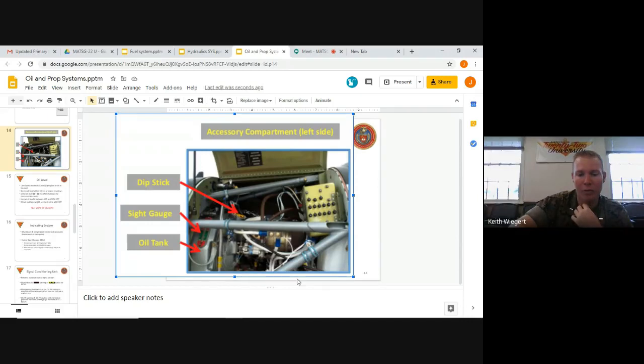Now, if I'm getting low oil pressure, my engine-driven low-pressure fuel pump is not working, right? If that low-pressure fuel pump is not working, then I can also assume that my external oil scavenge pump is not working as well. Well, if we've got problems with the oil system, if we've got oil that's not being circulated through the system appropriately, then what can we expect? Probably an imminent engine seizure.